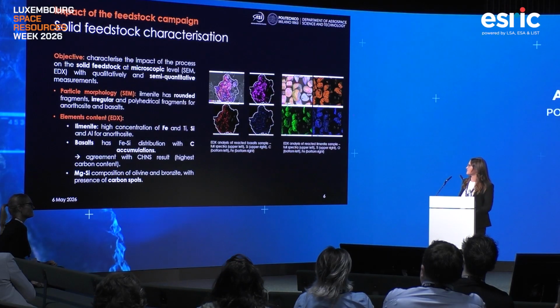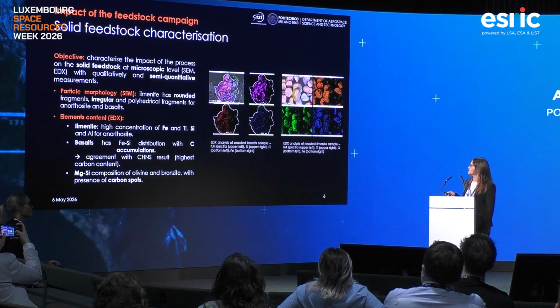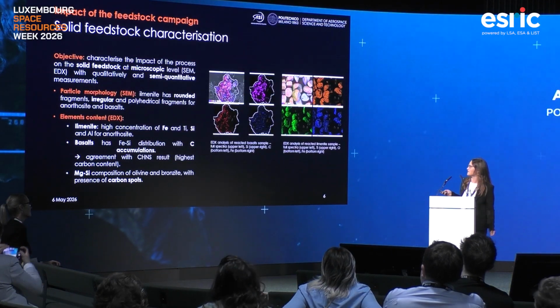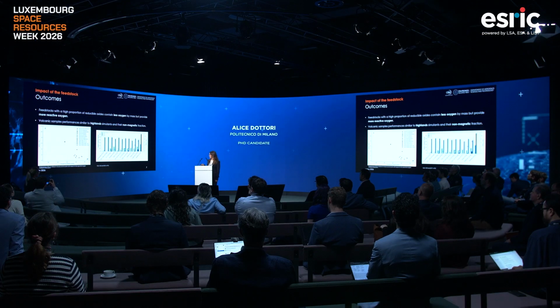After the process, we characterized the solid feedstock with the SEM and EDX, and we noticed the typical footprint of the process that are kind of glass spheres, silica spheres, that are not present in the virgin simulant. And also we can notice the carbon deposition that we are aware of also from a macroscopic and visual aspect of the material, because it's really darkened after the process, but also we have a confirmation through EDX. And this is a summary of the results.